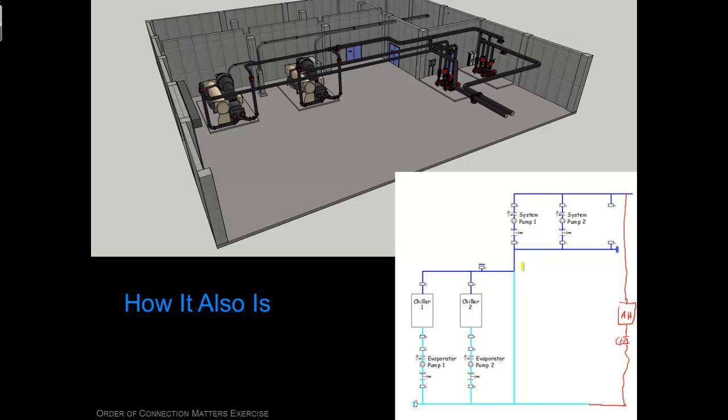If you look at this, there's actually two independent circuits here. If these pumps weren't running at all, and these pumps were running, and the valves were open on the air handling units, I could pump water around in a loop that kind of went like this. Okay, so that's basically a distribution loop, and these would be called the distribution pumps.